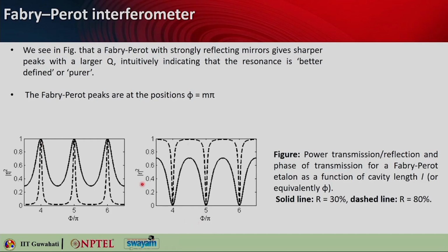If you look into the reflection spectrum, or capital R, which is nothing but the modulus of small r squared, you will see that there is a drop. So, reflection based, it is basically a band stop filter, but in the case of transmission, you can actually get band pass filters based on a Fabry-Perot cavity. Here the cavity length is taken care of by this phase.